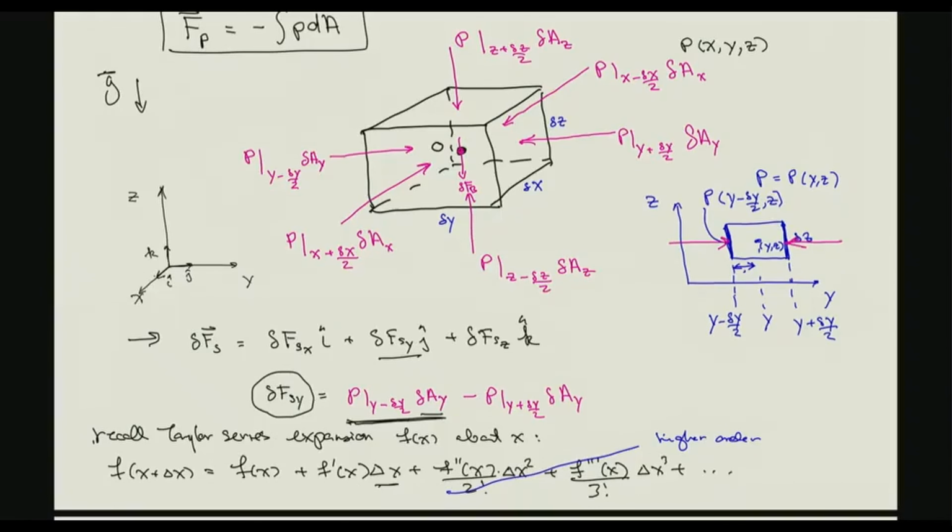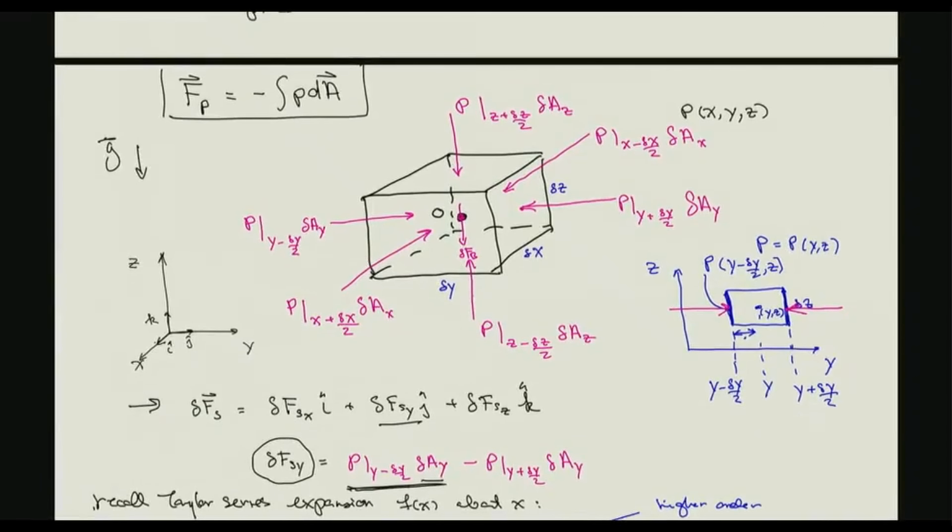All right. Now, the surface force is going to be due to pressure. And we discussed force associated with pressure last week, right? And so the differential force due to pressure is given by minus P dA. So the pressure acting on the surface, and here's the differential area, dA. And the force is in the opposite direction to the area outward normal. So this dA is a vector in the direction of the outward normal.